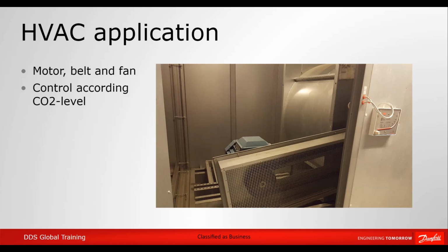Drive frequency reference control is according to the CO2 level. CO2 is increasing when people are coming to the arena. The higher the CO2 level is, the faster the motor runs.